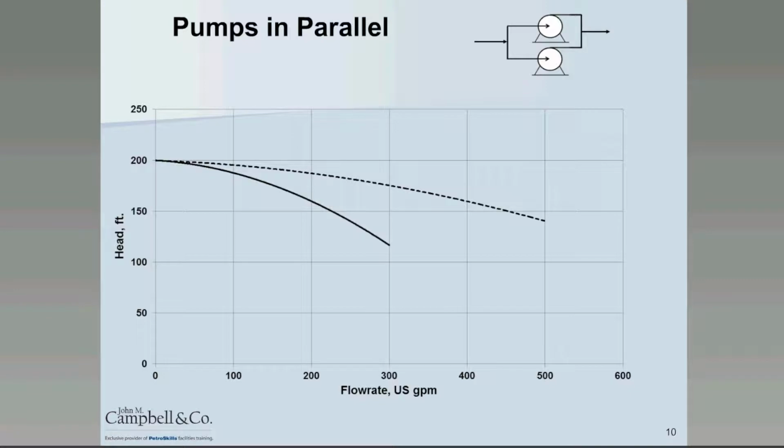flow rate. So drawing onto here my pump curve, you can see that the increase in capacity is going to be a direct function of the system curve. With my original system, one pump running gives 200 GPM, now with two pumps running I get about 230 GPM. So in this case, that's about a 15% capacity increase. If I had a different shape system curve, then that's going to have a very different increase in capacity. So it's very important that we understand this effect. And quite often this is overlooked.